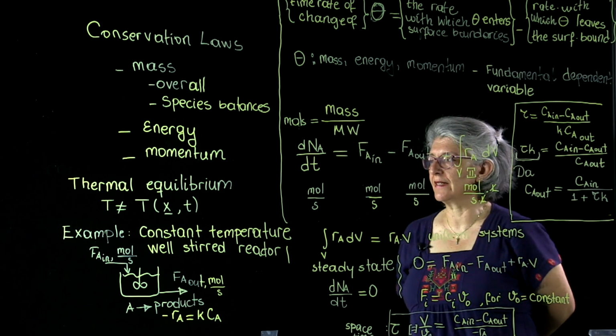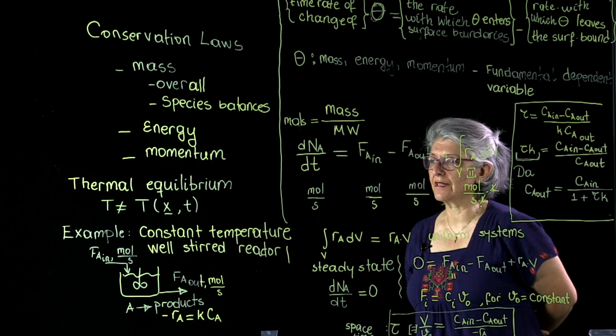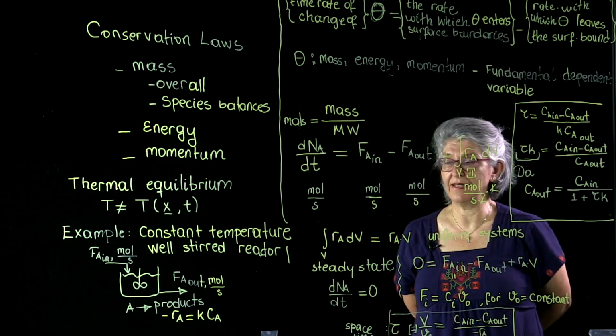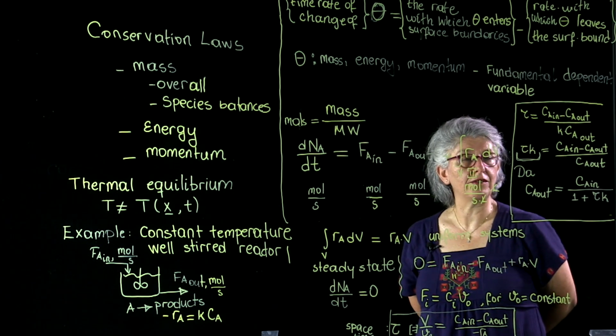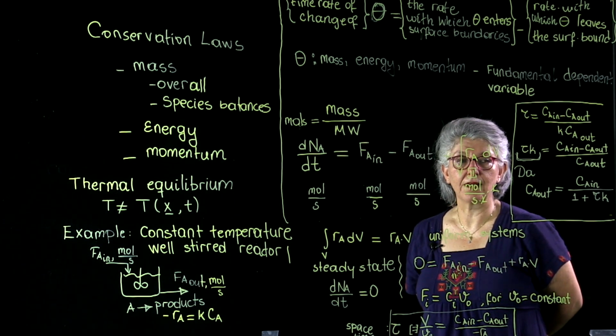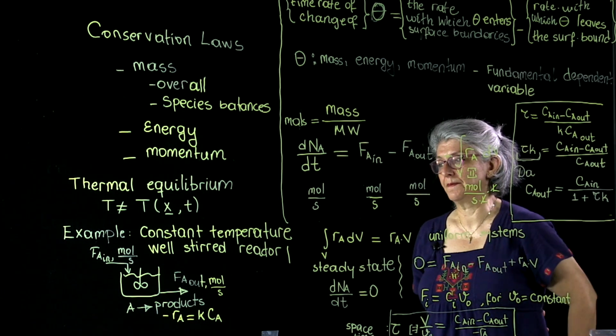This equation tells us that the outlet concentration of species A, the reactant, depends very strongly on the inlet concentration, on the reaction rate constant, and on the space-time.